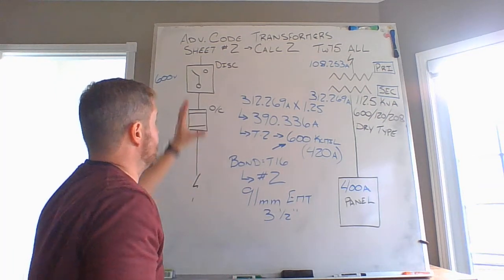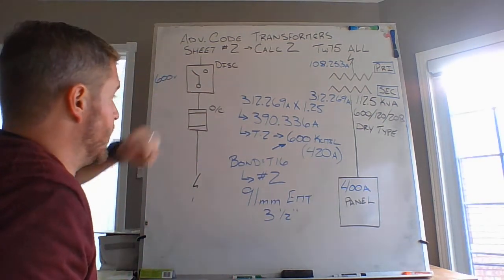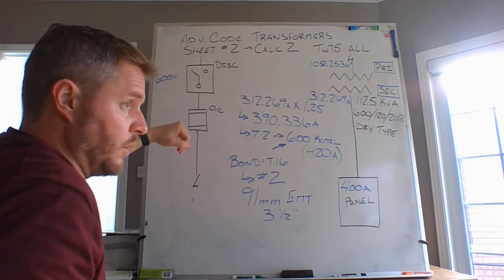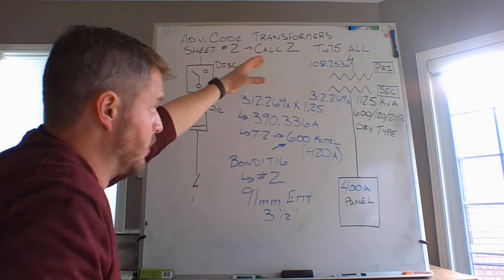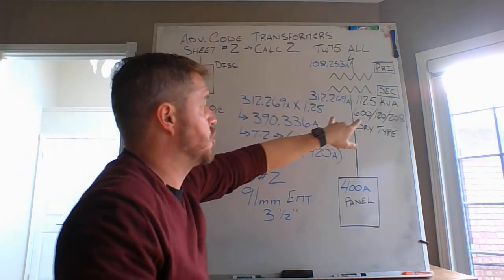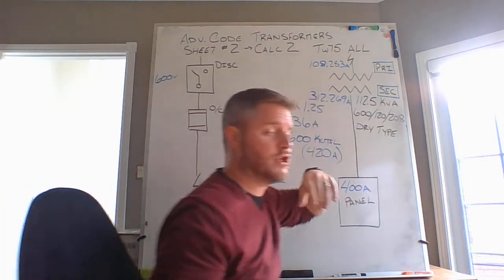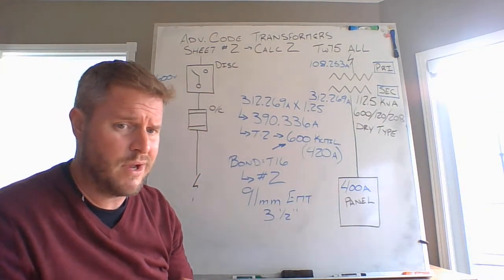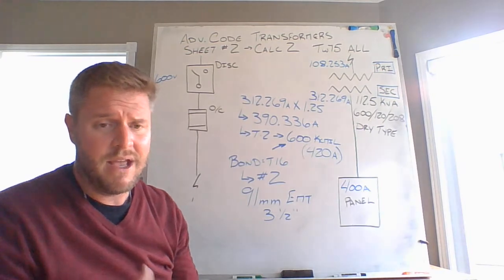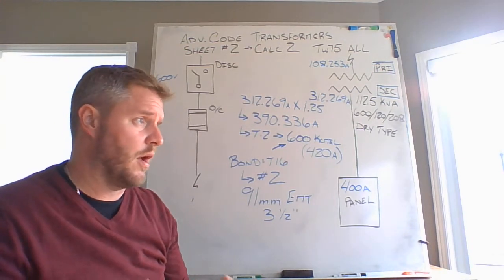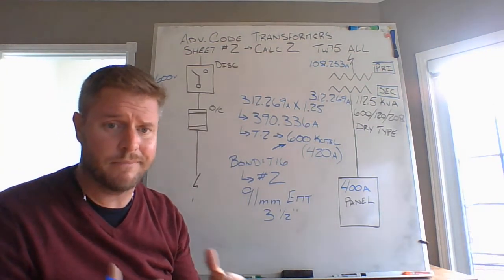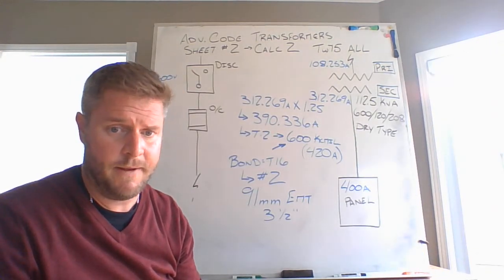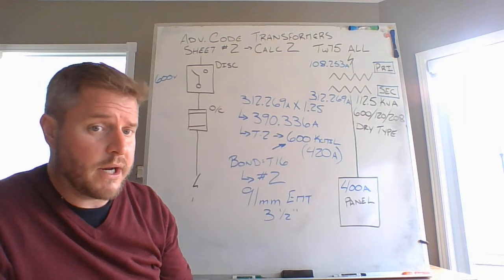All right, 200 amp disconnect, 600 volt side, 150 amp fuses primary. All right, 600 volt system, delta connected primary to the transformer, drop down, achieve your two different voltages, your 120/208, probably going to be the most common, whether you're 309A or 442, 120/208 volt stuff. There is a possibility for a 460 operation too, but that's okay. It all depends on your secondary voltage and what you're looking for. All right. So these are transformer calculations.